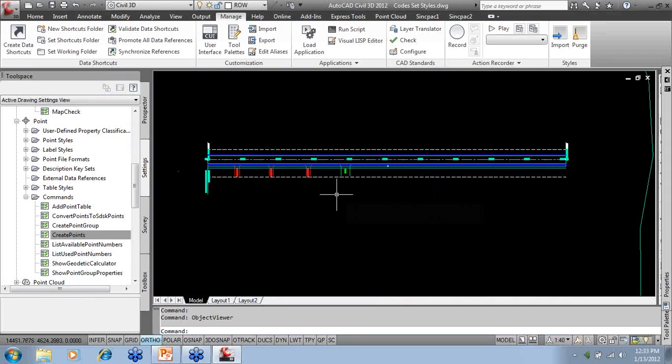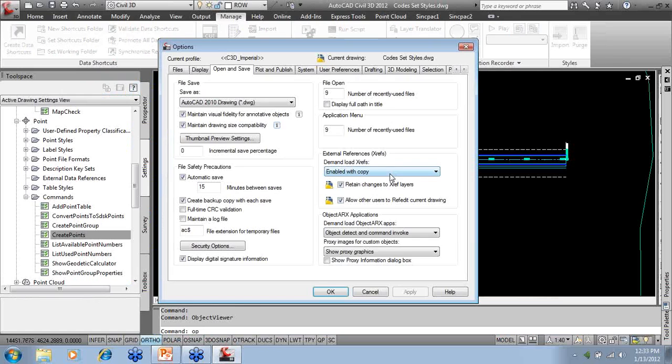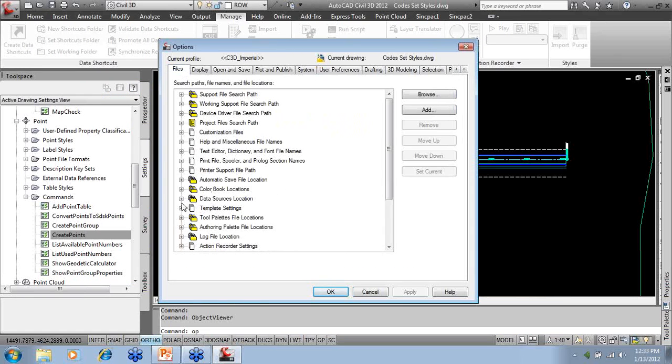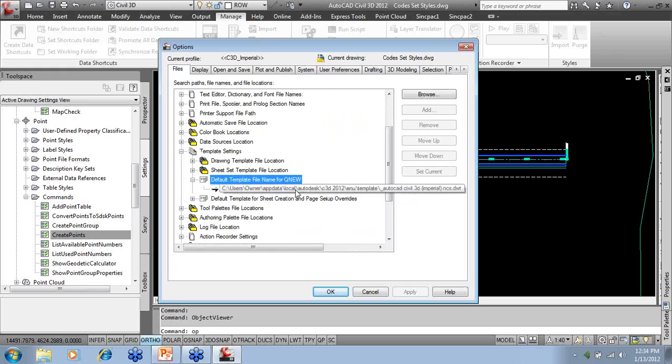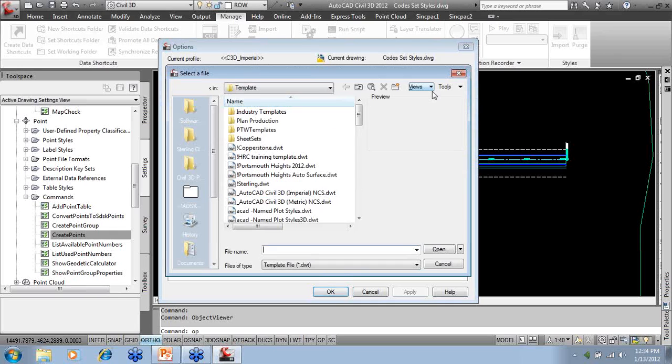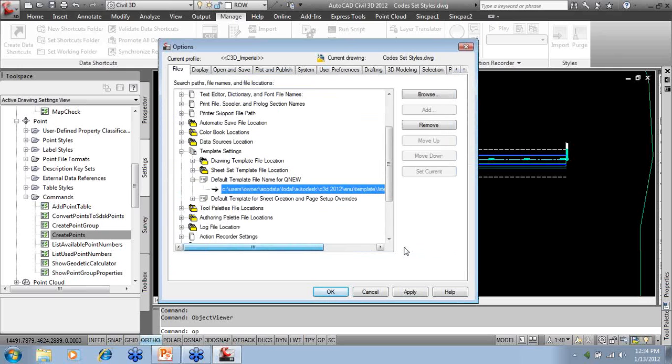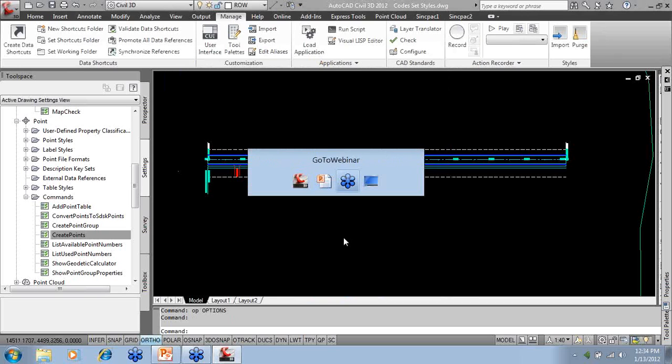And the last one, I guess, so you know, and most of you probably know, you go to your AutoCAD options, and if you want to hit the AutoCAD, just go up here and hit the new icon. Then you can go to File, Template Settings, and in here you can go to Template File Name QNew, and you go pick your custom template you just defined, and you can set that. The next time you create a brand new drawing, it will automatically use the template that you created, and they won't even know any better that they have other options. And also you can set that path to where your templates are set on the server.